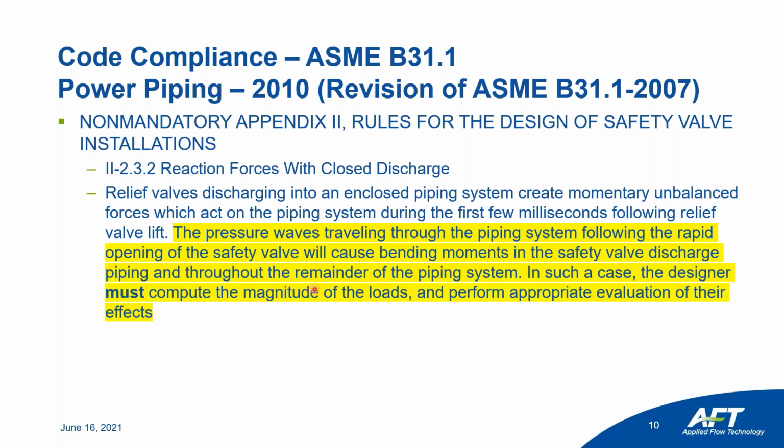In such case, the designer must, and it's interesting because this is a non-mandatory appendix, but it uses the word must, compute the magnitude of the loads and perform an appropriate evaluation of their effects. As you can see, it just warns you and requests you to do the calculation of the wave traveling when the relief valve opens, but it doesn't give you any guidance on how to calculate dynamic forces.